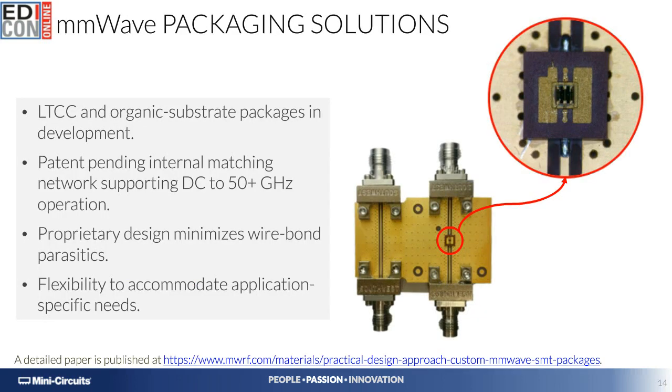This slide here is an effort that we have initiated as an internal need for packaging our CAT series of MMIC mmWave attenuators. Those CAT attenuators are readily available in die form currently on our website, but we wanted to provide our customers with a full turnkey package solution on the same. And we quickly realized that a plastic QFN approach would act to the detriment of the actual performance of these attenuators.